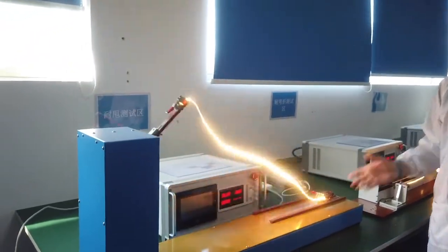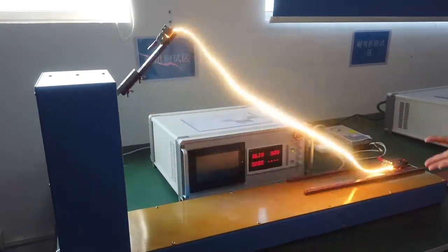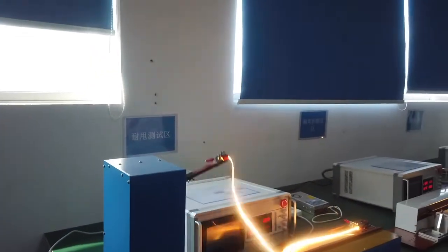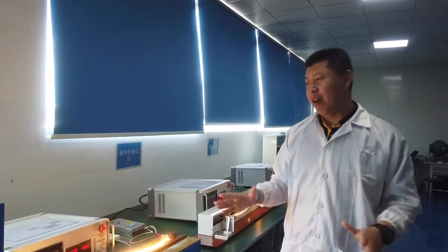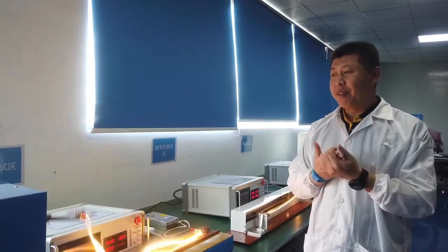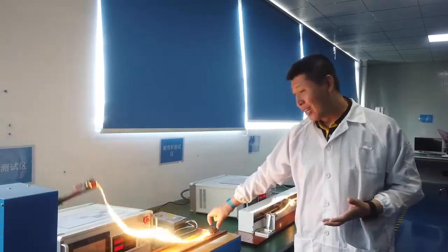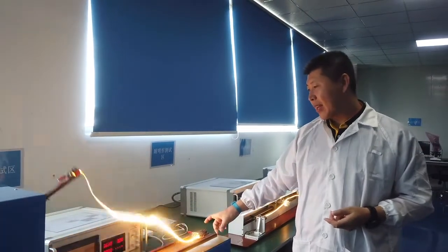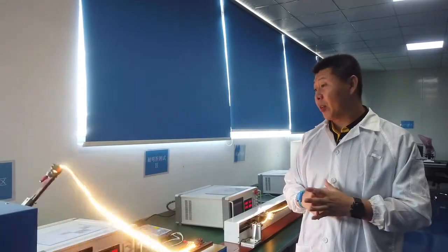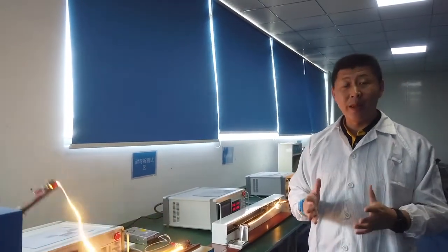And the last one is the shaking. We call it the shake test. So you see, we need a precise speed per minute, such as 1,000 or 2,000 times per minute. And also we need the data after the test. First, the physical appearance, the glue for the CUV, the LED, the soldering for SMT, and then we will test whether it lights normally or not.